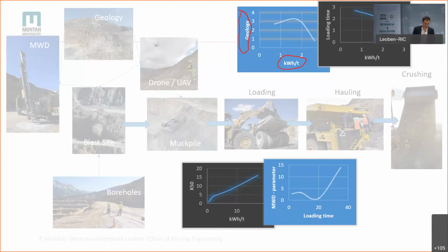Just as an example, I got to read a manuscript 2 or 3 weeks ago where somebody was comparing the digging time and analyzing the digging time of a wheel loader into the muck pile. The difference in the digging time was marginal. It wasn't a couple of half seconds or seconds, depending on the difference in the muck pile. But if you take a look at the entire mining operation, and if you have 10,000 digging events a day, half a second doesn't really count, because then you have moving backwards, moving forwards, dumping on the truck, spotting, idling, preparing your muck pile.